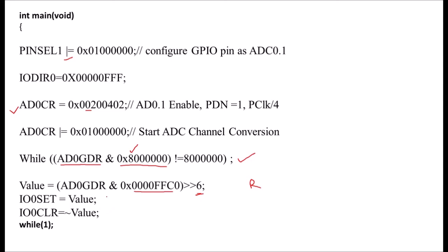So in almost all programs we have used this logic. For example, suppose you want to set, I am considering only 4 bits, actually it is 32 bit or 10 bit. If you want to set these bits, we'll send this data as it is to the set register. Here I am considering only 4-bit data, it is the same for 8-bit, 10-bit, 16-bit.